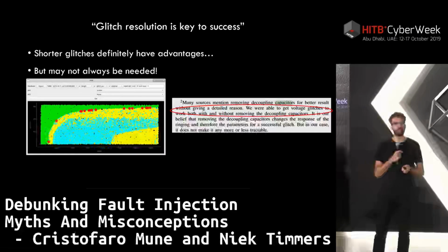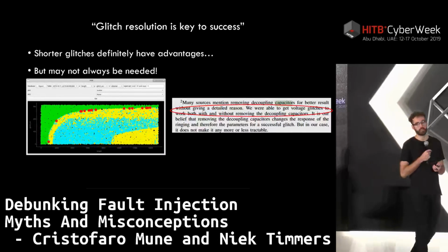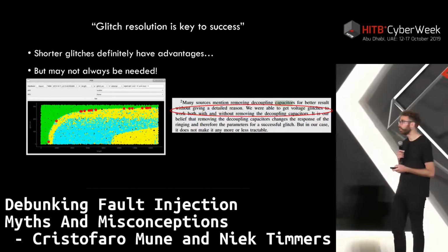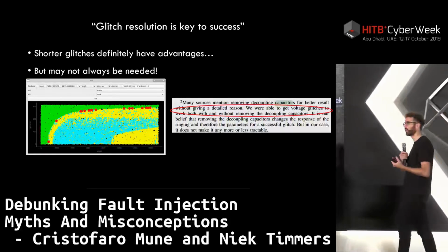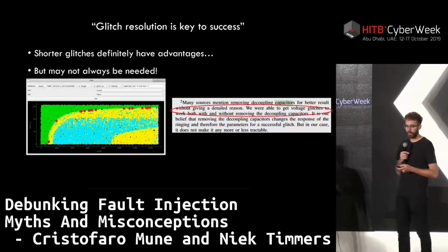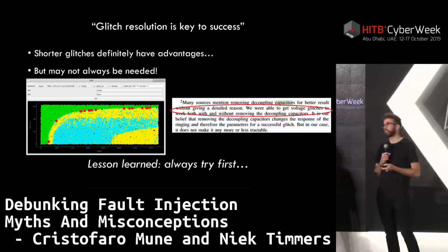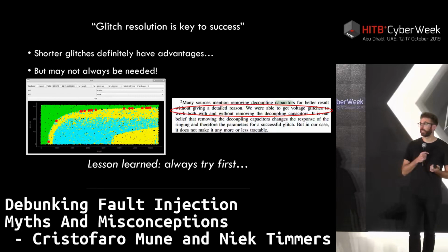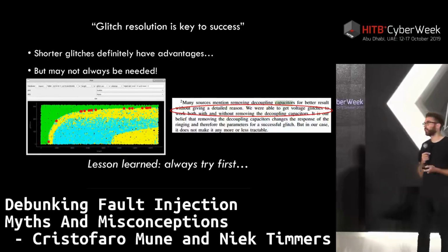So there he made the conclusion similar to what we usually made, that it's not always needed to make sure that the glitch is as narrow as possible. The key lesson here is just start first trying before you actually start modifying your setup. Because if you start removing capacitors from the target, you get other trouble as well. Your target might not boot anymore, or your target may become unstable.